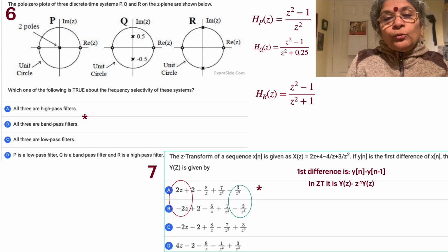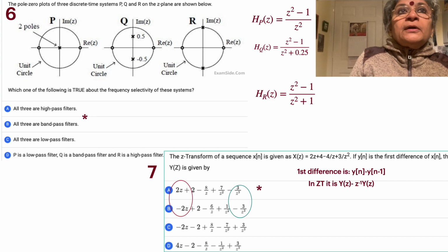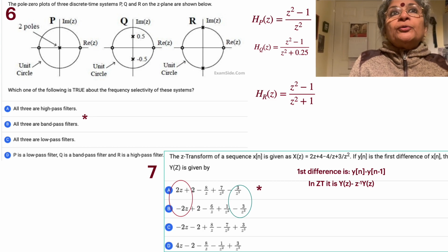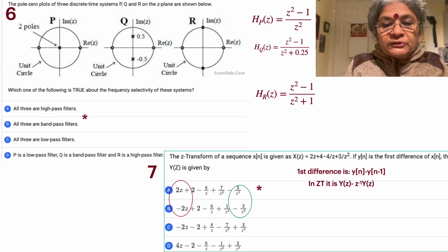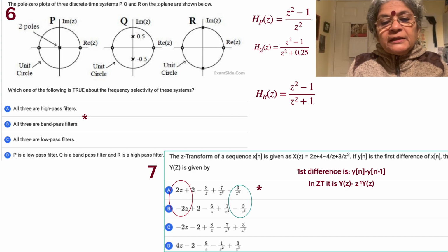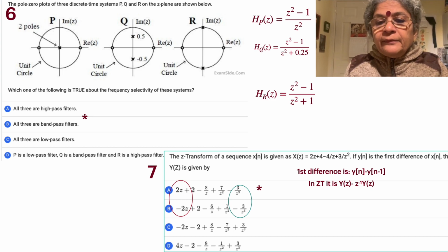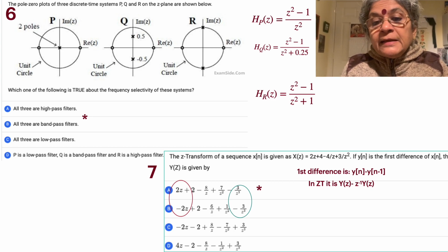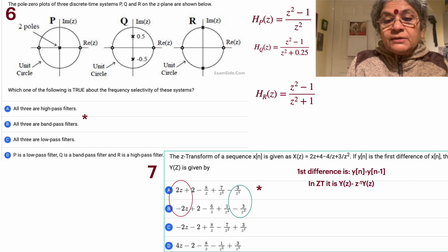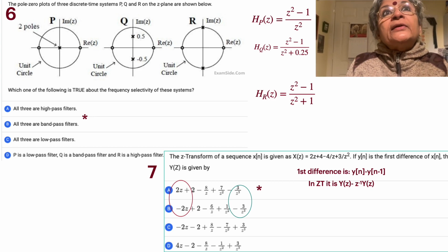So we have two extremes for the function as given in the Z transform domain: the one with the largest exponent and also the smallest exponent for z. We have several options, so rather than computing everything, it's better to go for the two extremes. At the other end, we have 3 z raised to minus 2 as such, and when you multiply it by z raised to minus 1, you get z raised to minus 3.